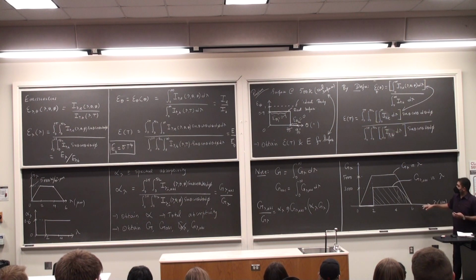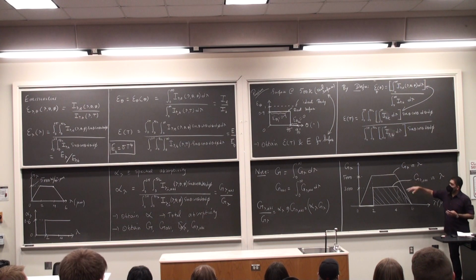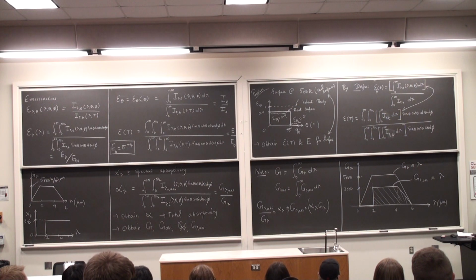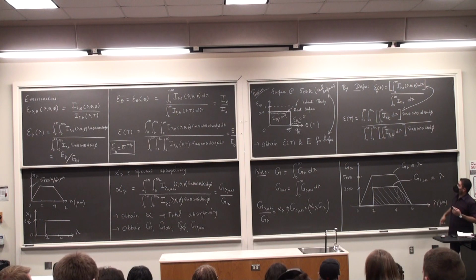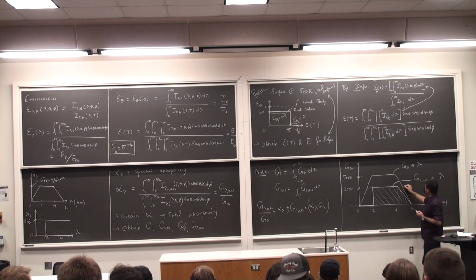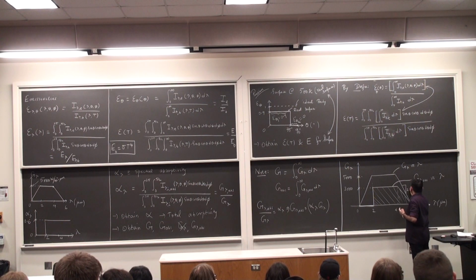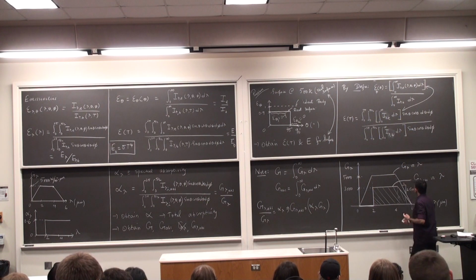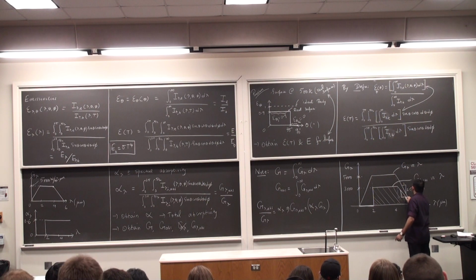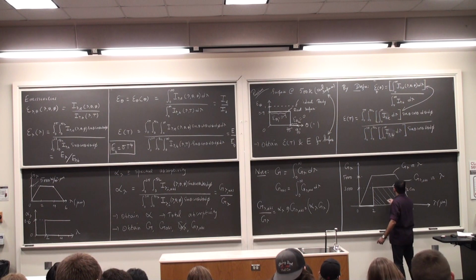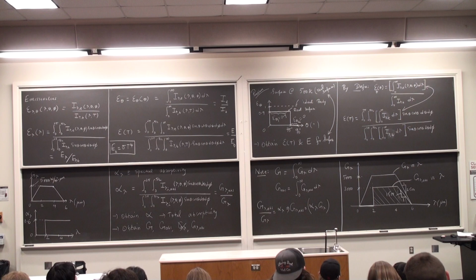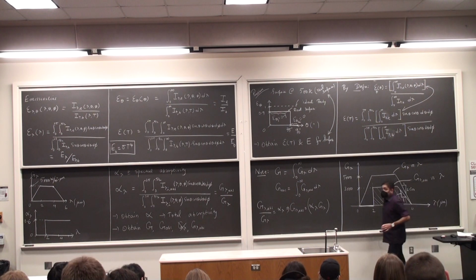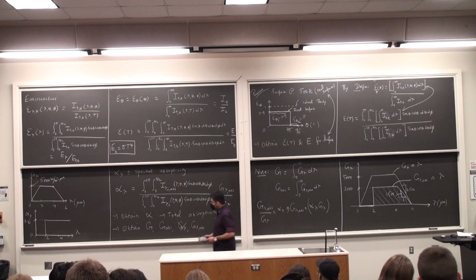And then from 4 to 6, the slope of this is going to be reduced by a factor of 0.6. Okay, so if the slope was 5,000 by 2, so that's 2,500 was the slope for this guy, this will be 1,500. That will be the slope of that. Okay, 2,500 times 0.6. So once I have those two, then we are pretty much good to go.